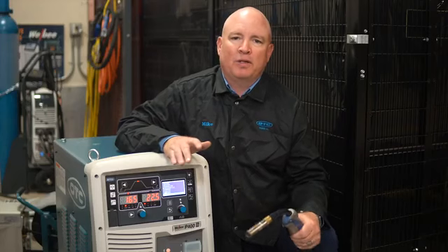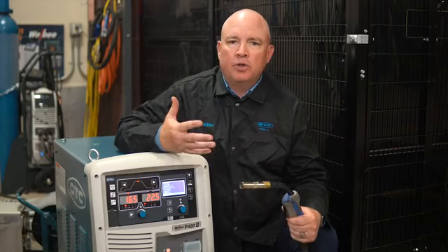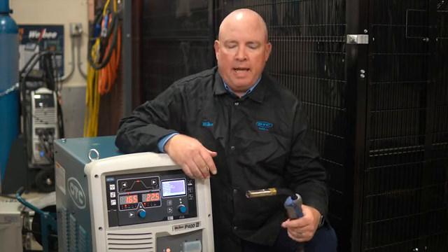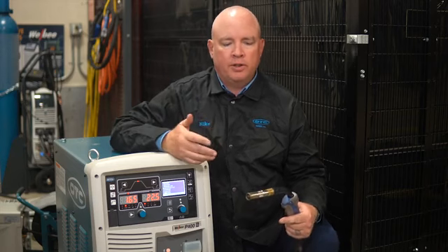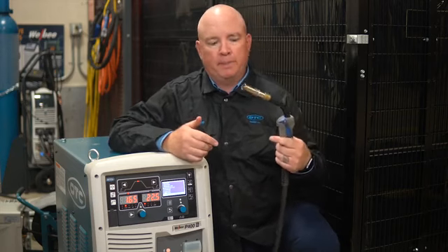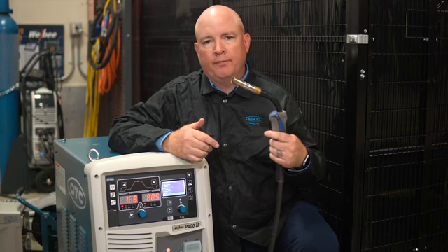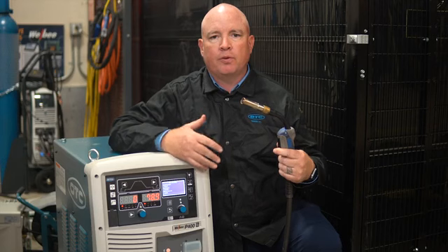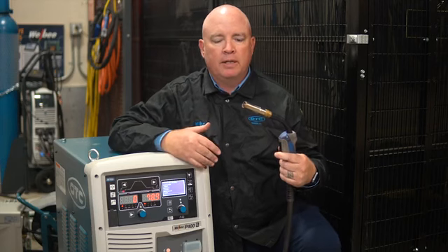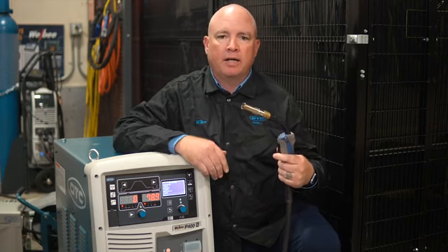Have you ever run out of weld wire and then you have to load new weld wire into the machine, and so you put the new spool on the wire feeder and then you have to get the wire run all the way through your weld gun? Most of the time, people end up pulling the trigger. Unfortunately, this is a very slow process. It takes forever for the weld wire to get through the gun, and it also creates a live contact situation.